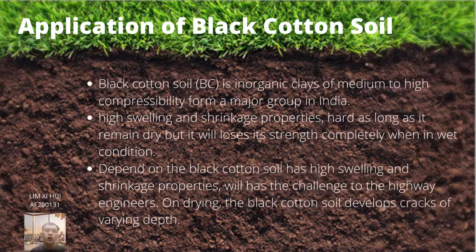The application of black cotton soils. Black cotton soil is an inorganic clay found in India, and it has high swelling and shrinkage properties. Depending on the swelling and shrinkage properties, it poses a challenge to highway engineers.